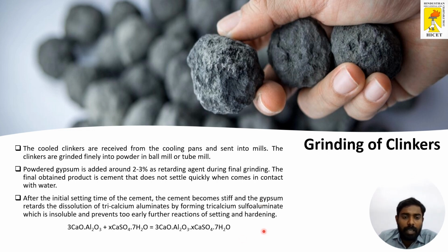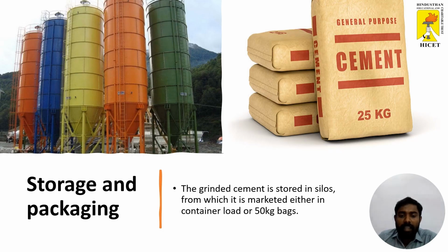After the initial setting time, the cement becomes stiff, and the gypsum retards the dissolution of tricalcium aluminate by forming tricalcium sulfoaluminate, which is insoluble and prevents too early further reactions of setting and hardening, and this chemical reaction is given here. The ground cement is stored in silos, from which it is marketed either in container loads or maybe in